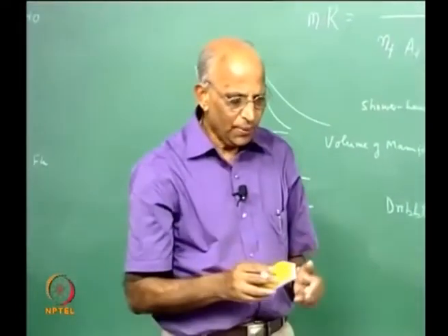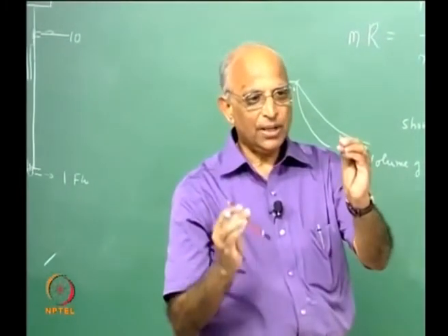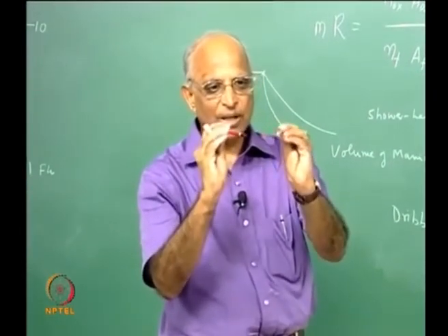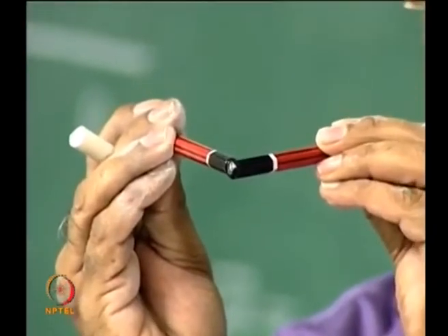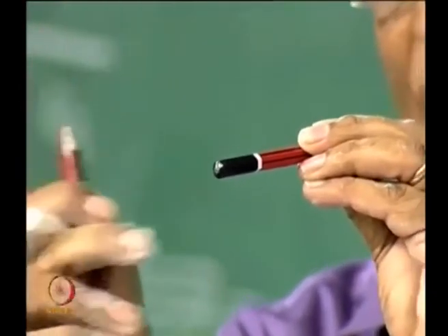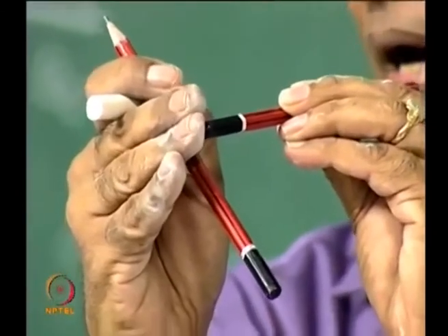What do we do? Let us say one stream of jet is coming like this, the other stream of jet coming like this. Instead of having these jets coming like this, we make them interact with each other. That means we have impinging jets, and once you impinge the jets, a fan is formed over here, and that becomes a thin fan, and that is what begins to burn.